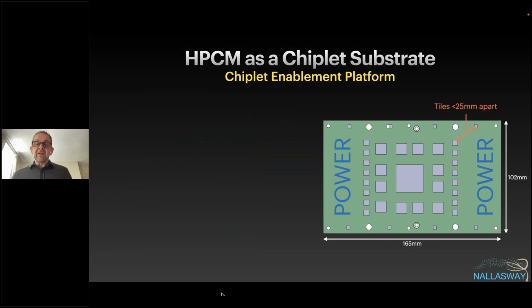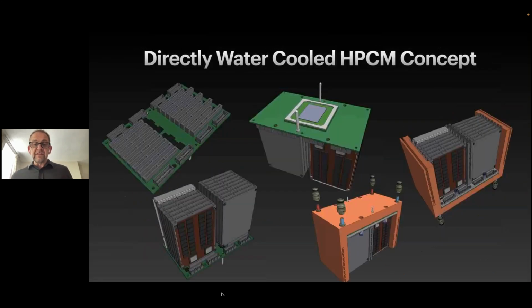Exactly. And by the way, that's really the whole idea of these modules. If you look at the proximity of these media modules with their controllers to the big chip, you're in the region of 5 to 10 dB apart. IBM kindly did a simulation for us, and we were sub 10 dB for PCIe Gen 5. I think it was about 7 dB if we unpackaged the chip, the processor chip, and put it down on the substrate on the OEM.